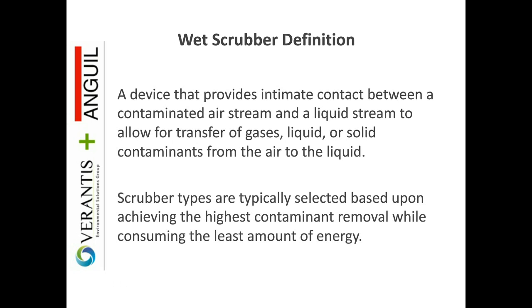So we talk about a wet scrubber, and let's go through a real quick definition here of what exactly we're talking about. It's essentially any device that allows us to extract particulate, solids, liquids, gases from a gas stream and transfer it to the liquid phase, whether we simply dissolve it, we neutralize it, or it's just a solid that's captured there. So obviously what we've been talking about here with thermal oxidation emissions are contaminant acid gases. We're generally looking to absorb and neutralize those compounds into our solution.